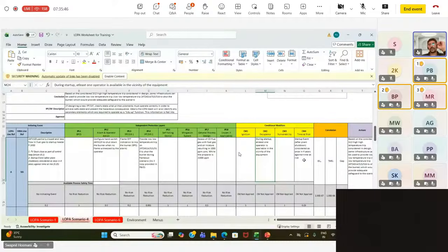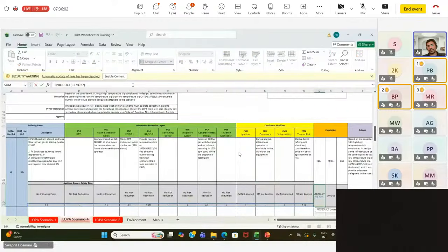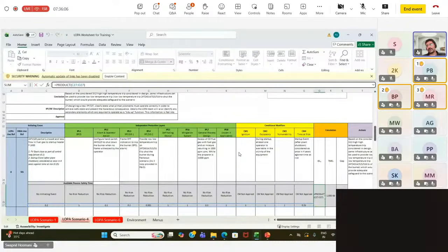So when we are saying one time in 4 years, you have to provide a time at risk against every year. So that is why it is one time in 4 years, which gives you a factorization of 0.25. Fine. So based on this, what you get is the sum of all the products of these, and that is 1 into 10 raised to minus 7.